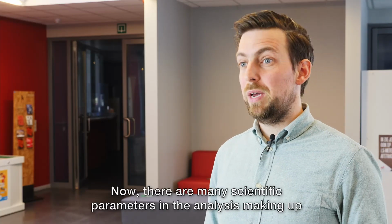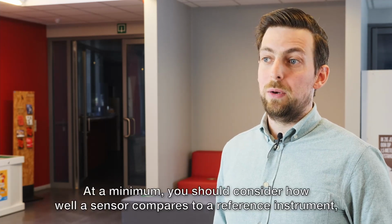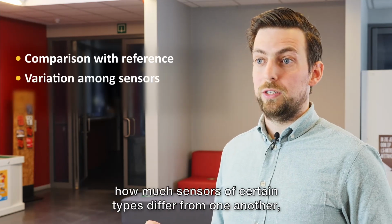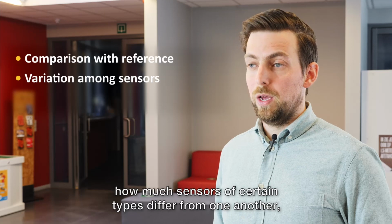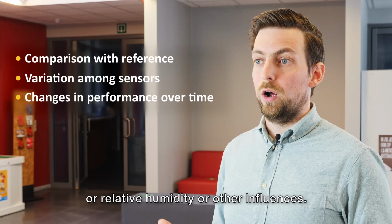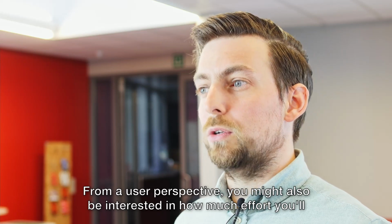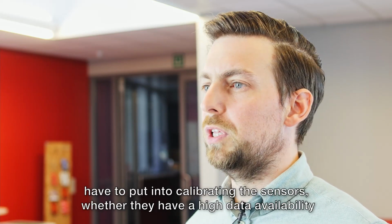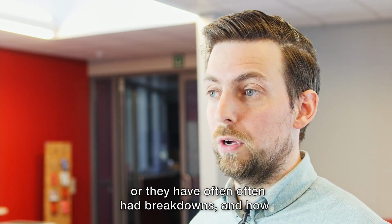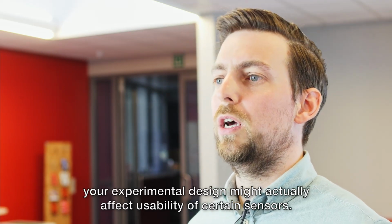Now, there are many scientific parameters and analyses making up individual sensor performance. At a minimum, you should consider how well a sensor compares to a reference instrument, how much sensors of a certain type differ from one another, and whether this behavior changes over time, for instance due to drifting or relative humidity or other influences. From a user perspective, you might also be interested in how much effort you'll have to put into calibrating the sensors, whether they have a high data availability or they often have breakdowns, and how your experimental design might actually affect usability of certain sensors.